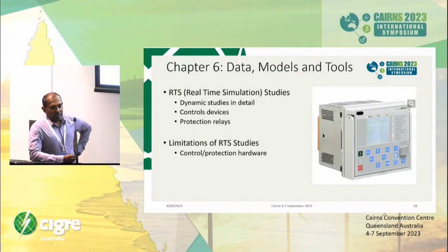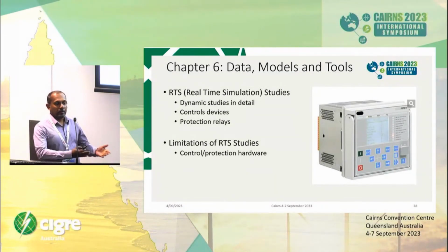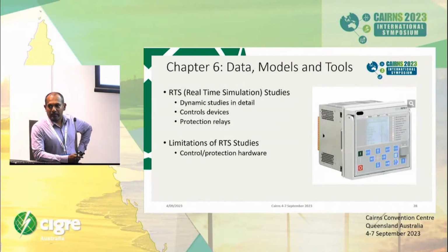Real-time simulations give you obviously more insight because you can engage with the hardware in the loop, with the actual controllers and the protection relays. But the limitation is that most of the time the replicas of these protection relays or control systems may not be available. If it's a new project, yes, probably, but black start is kind of dealing with the existing equipment in this power system. So it's a huge challenge.